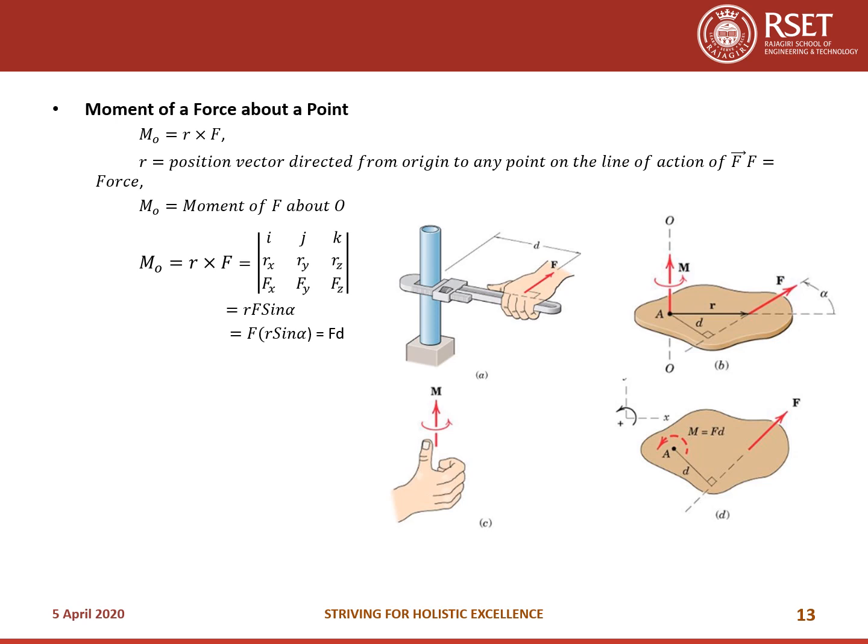Now, the second case, case B, will be much more clear. There you can see that the position vector r is up to the point of the force F, and F is at some angle alpha. If that angle is alpha, the inner angle, also marked in yellow, is also alpha, and you can write sin alpha as d by r. So d is equal to r sin alpha. So it is nothing but F into d, and d is the perpendicular distance, right?